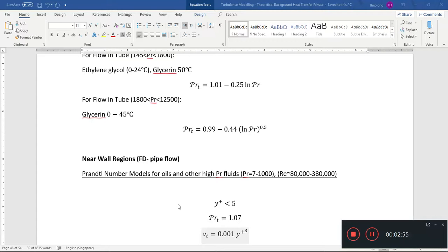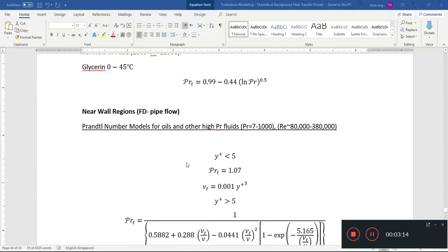the heat transfer from the wall suddenly becomes very important, because that becomes the driving force of the flow. And when that becomes the driving force of the flow, you have got to get your boundary layers and everything correct. So when natural convection comes in, you have to pay a little bit more attention to this Prandtl number. Otherwise, in forced convection, you can sort of get away with it, and most of your CFD code would still give you more or less the right results. But just beware when natural convection is significant. You need to pay attention to the turbulent Prandtl number near the wall. So this is what this video is about.